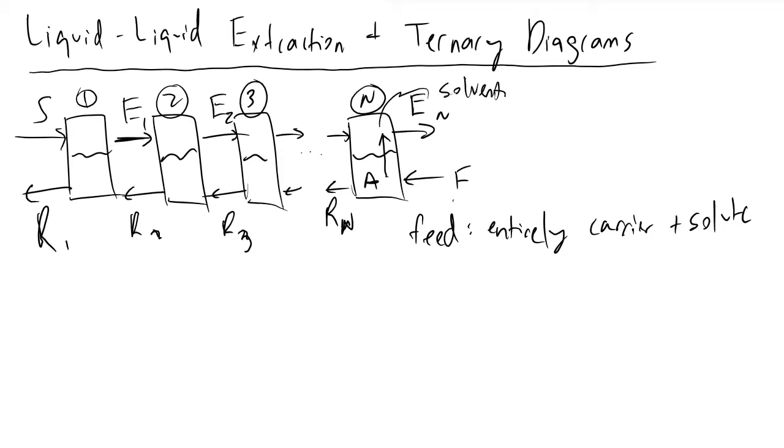We will have our most concentrated extract interfacing with our most concentrated feed, and at the other end of our liquid-liquid extractor, we will have our most dilute retentate contacting our least dilute solvent.